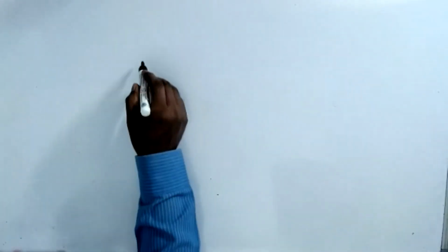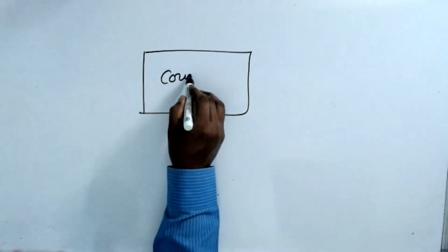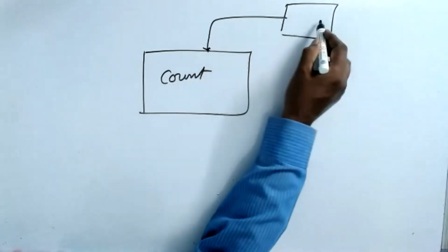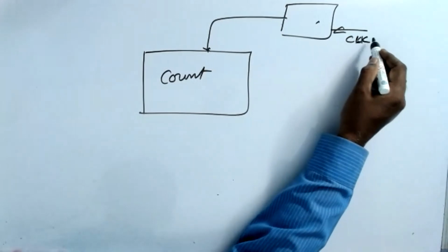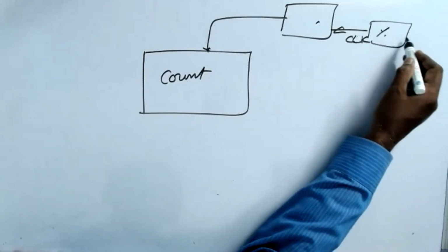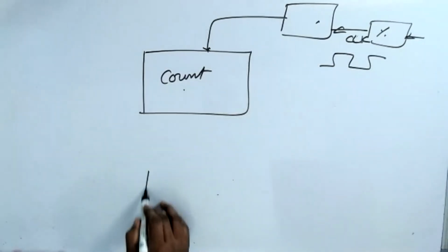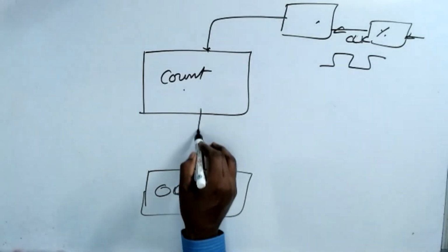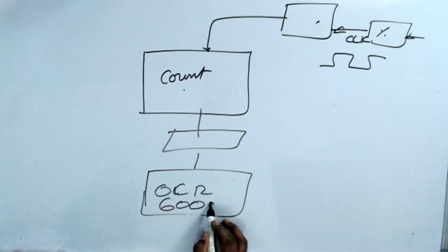You see here, we have a count register that is counted by somebody who has given a logic. This takes a clock. That clock can be divided by any number, because if you change the width, you will change the count. Then I have an output compare register. Both are getting compared. Right now in our code, we fix this to 60,000.